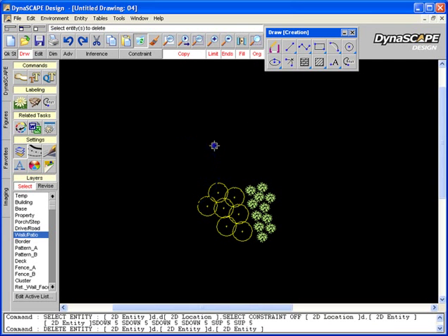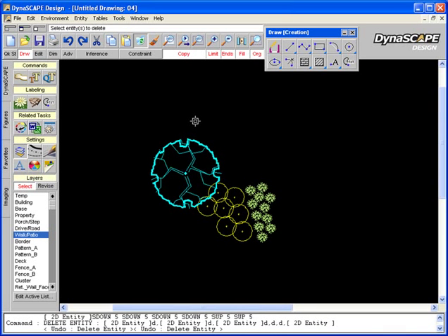You can continue removing as many objects as you like. You can click on several of them, remove them like that. To undo things that you've done, say for example, you didn't mean to erase those objects, you could use the undo keys over here, or if you're still within the tool that you're using and want to undo the things that you did with that tool, you can hit the delete key on your keyboard. It will undo one step at a time. So just by hitting the delete key on my keyboard will undo a command while I'm still in it.